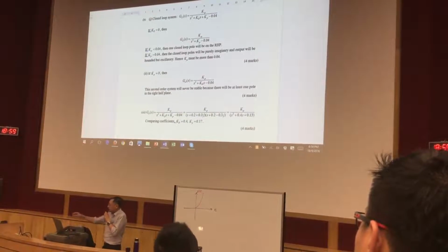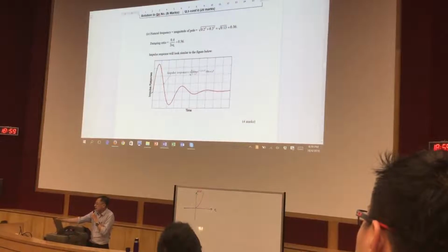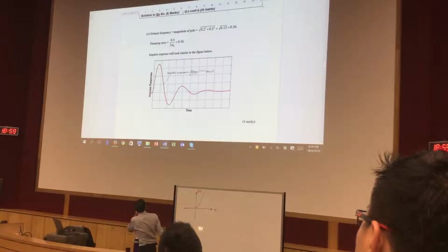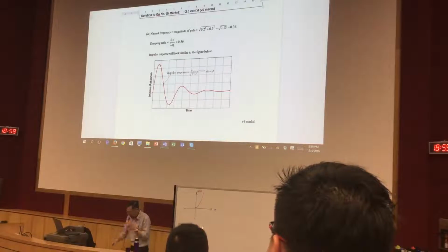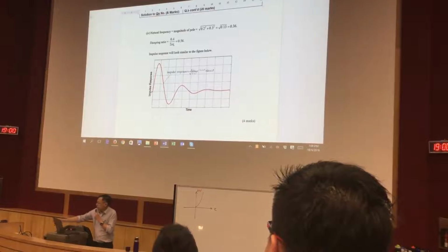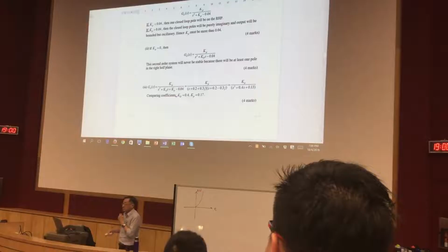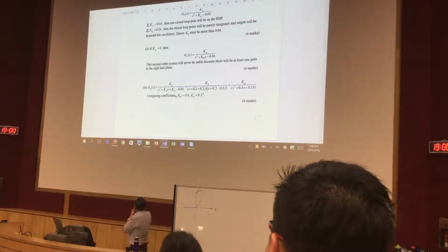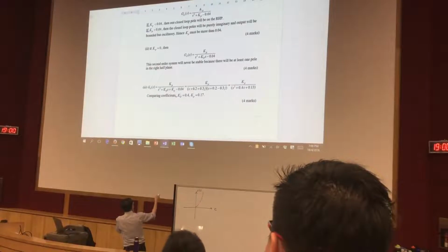Alright, okay, and then the last part is this part over here. So it will have a damping ratio, damping thing. And you will find that it will stabilize at 0. Why 0? If you look back at the expression here, say it's an impulse response, right? If you do the limit of S times this, when S goes to 0, you get 0, right?